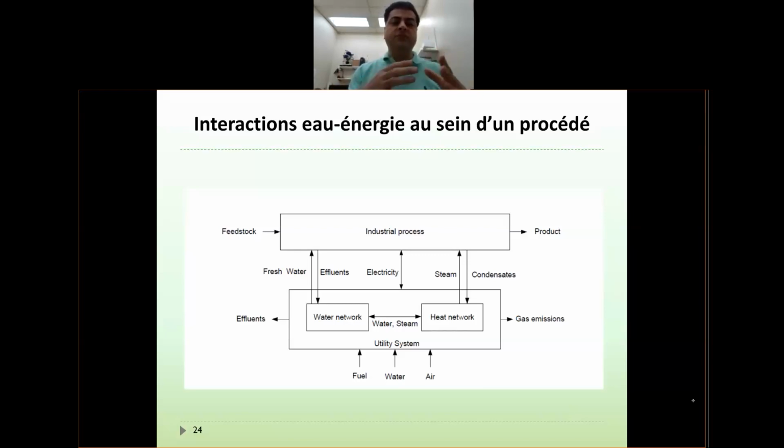So we have maximum process-to-process heat exchangers and minimum usage of utility. So we want to have minimum cooling and minimum heating by cooling water, steam, and whatever. That's why we said, okay, we have to do optimization to find the minimum temperature difference in the network of heat exchangers that we call delta T min, and then we move on.